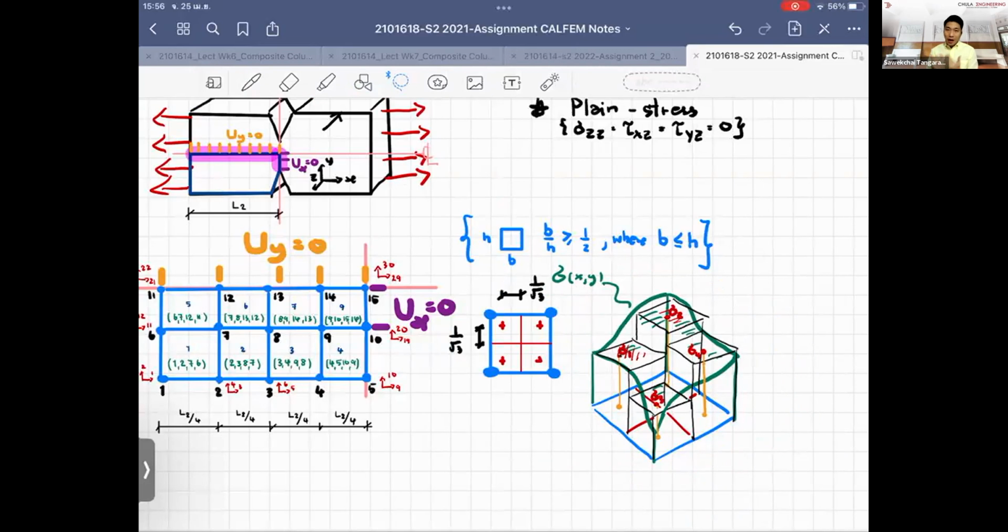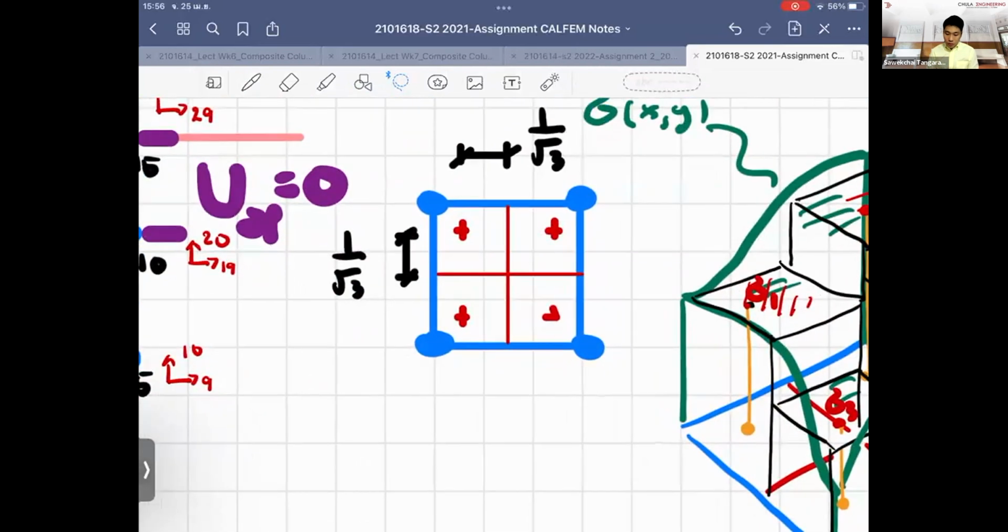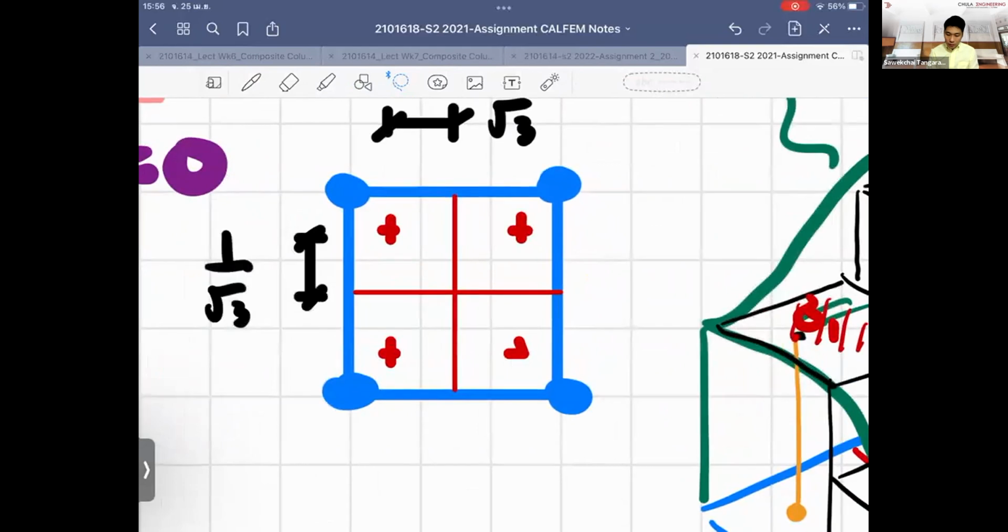So that's why people make a couple of efforts. One way is to allocate more Gauss points inside the element domain. But having more Gauss points is not simply putting in the Gauss point allocation. You have to increase the level of the nonlinear function you use.